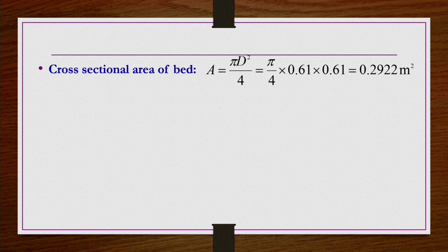Very simple: you have to find the Reynolds number first, to see whether it is in the low flow region or the high flow region, so that you can use only that particular part. To know the Reynolds number, you need the superficial velocity, at least V naught bar, but it is not given; rather the mass rate is given.